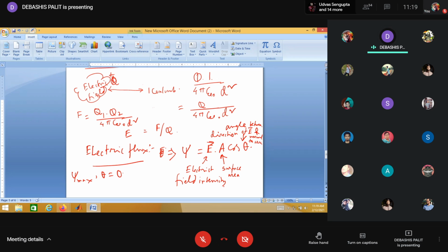So whenever theta is 0, so perpendicular flux linkage is carried out, then the electric flux is more. Electric machine design criteria is based on this more flux linkage and more compact design of the machine. So whenever more flux linkage is there, more torque is experienced, and torque per weight ratio is comparatively more. So design criteria is the torque per weight ratio of an electrical machine.